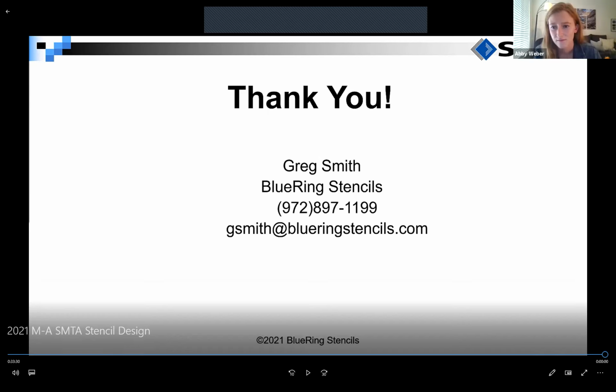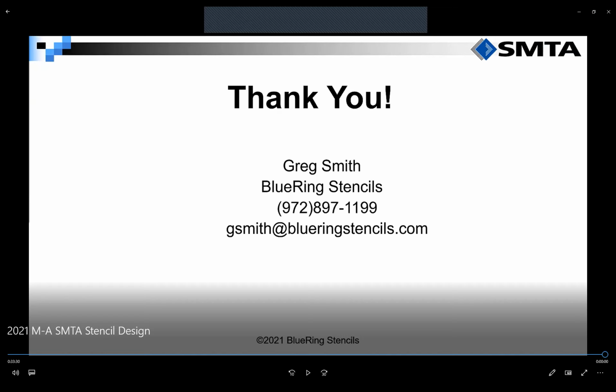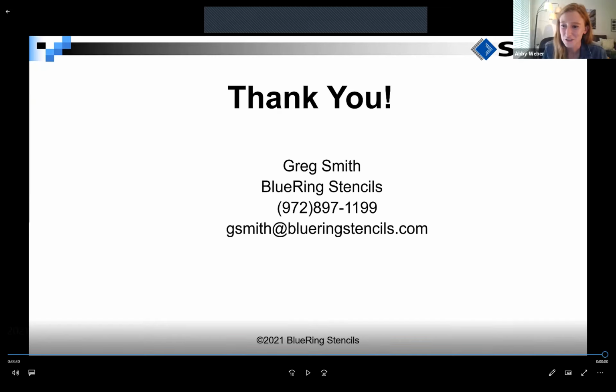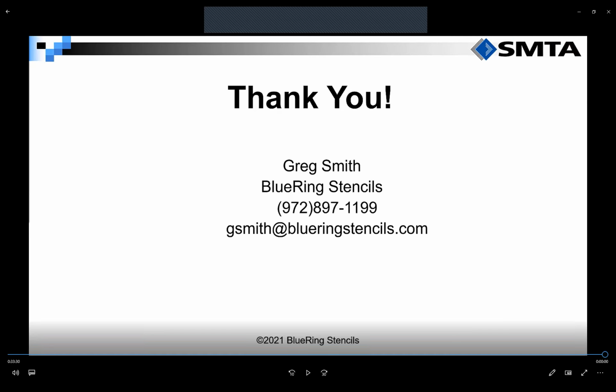Awesome, thank you. For step stencils, can the keep out dimension be affected by the mechanical properties of the application blade? Read that one more time so I can think about it. Sure. For stepped stencils, can the keep out dimension be affected by the mechanical properties of the application blade? I guess maybe what we're talking about is, if we applied more downward pressure, would it help that squeegee conform down into the pocket quicker?